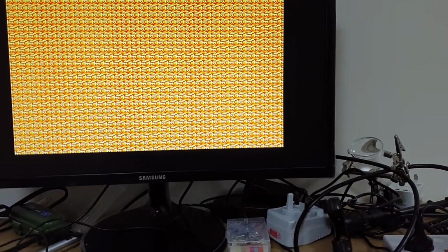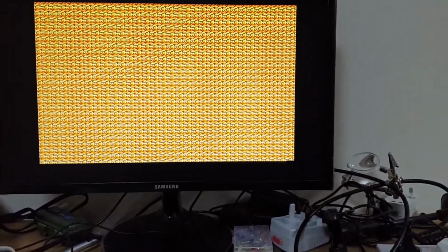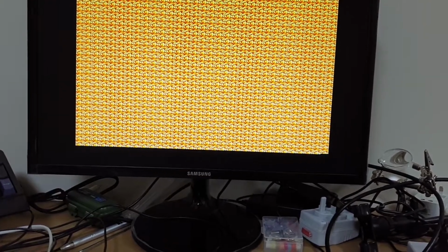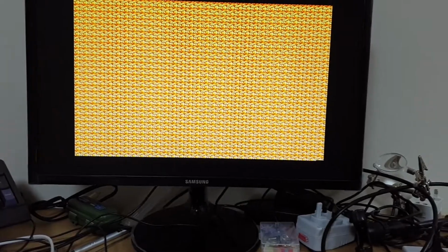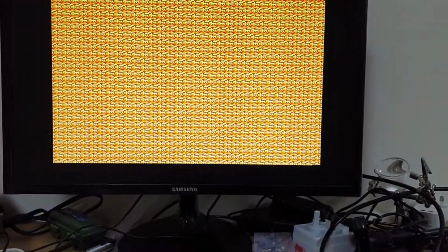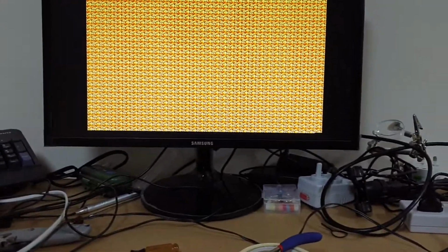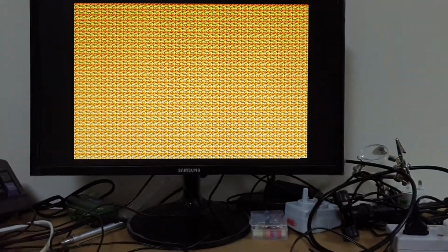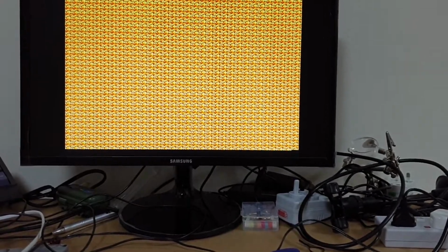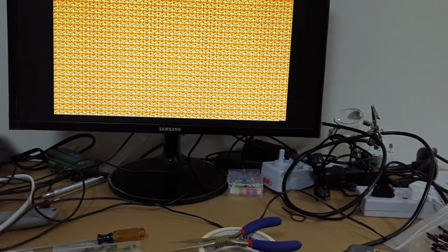I've tied the border X low now, definitely, and I'm going to tie the border Y low. Can I connect this with one hand? Maybe, potentially. I've noticed that the join on these wires is not that great. For some of them, there's probably a little bit of inconsistency from the manufacturing process. So there we go, I've tied both of these wires low now. Now if I grab the insulation, there's little indication of any interference. Actually, the screen is nice and rock steady, even with this huge, great big ribbon cable here, which is really good news. And here too, likewise, it looks good.